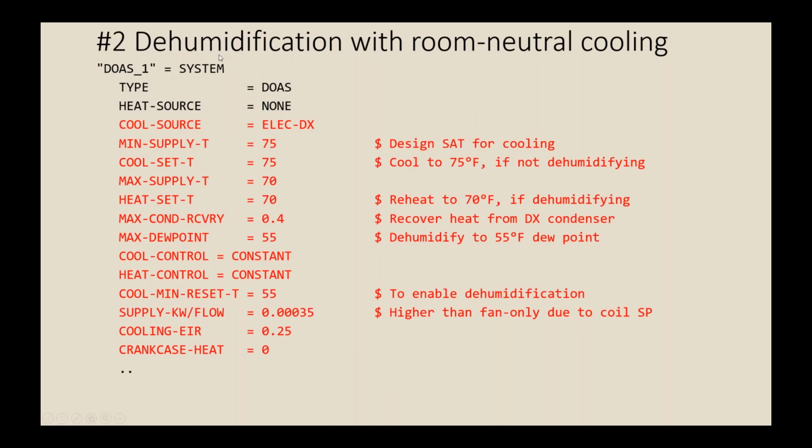Case number 2, we're dehumidifying the air to room neutral. So everything that's red is a change from the previous case. And I've got some comments off on the right. This supply temperature ranges from 70 to 75 if there's any call for cooling.